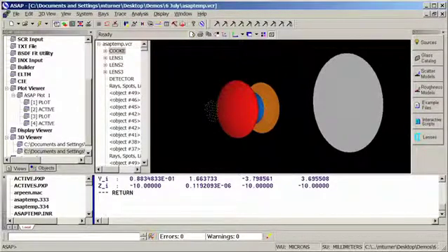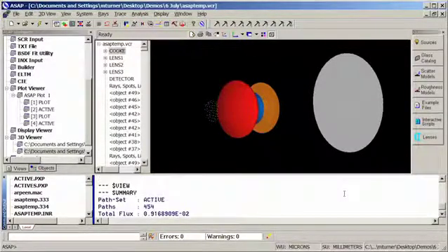And then we can also look at the detector and get an idea of the spread of the energy across the detector. By using the summary command, we can also get information about the energy, the total flux on the detector. And when I know that I initialized my energy to have units of 1 watt, this tells me that there is a very small amount of that energy actually making it to the detector as these Fresnel reflections, and that they're highly dispersed across that detector surface.